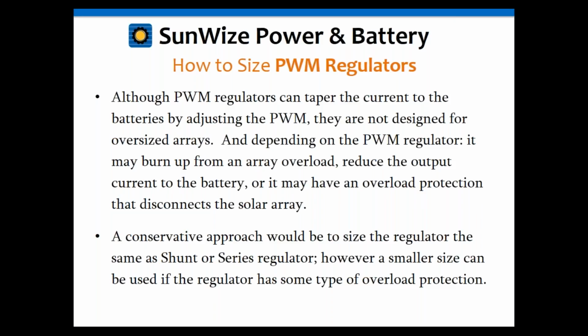Most of these regulators have 2 to 5-year warranties, sometimes even more, and they have up to a 10-year design life depending upon the model and the manufacturer. But that design life can be reduced dramatically by running it at its maximum all the time. So just something to consider when you're sizing your regulator, that it may be just a few dollars for the next size up, and it may end up extending the life of your regulator, so it may be worth the extra money to do that.